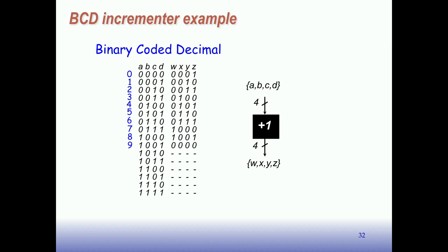And just a little preview, when we make our Karnaugh maps for these 4 functions, we put these dashes in the Karnaugh map, and we can make that dash be a 1 or a 0, whichever one makes our circuit simpler, gives us bigger groups of ones, or gives us the opportunity to group more ones together. So that's kind of the key here, is we can use these don't care conditions to help us simplify the circuit. And we'll do that next week.